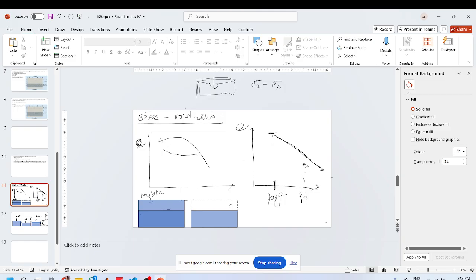Let me have a normally consolidated soil. PC1 is the pre-consolidation pressure. After I load this soil, it will show a steep reduction in void ratio like this. Now I'm unloading the soil, so it will regain some of its compression back. Not all of it, some of it. Now, the pre-consolidation pressure of the soil is PC2.